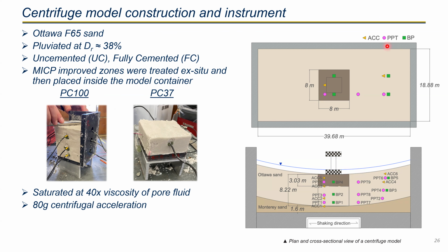And we instrumented accelerometers and pore pressure transducers to monitor the dynamic behavior during the test. After building the model, we saturated the model container with a fluid 40 times the viscosity of water, following the scaling law of the centrifuge test. And we did the test at the ADG.